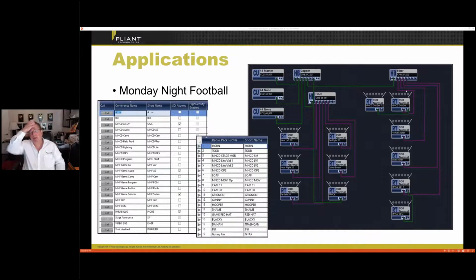So in this particular configuration, they use a single fiber. One of the reasons they use a single fiber duplex is because a lot of stadiums, while they have fiber, don't really have enough fiber because so many companies are using it now. When they laid it in, they didn't have enough ports. So they'll go with a single mode fiber. They will go out for distribution to the field where they have a separate cart that then picks up each one of the fiber strands and lays it out to the different transceivers.